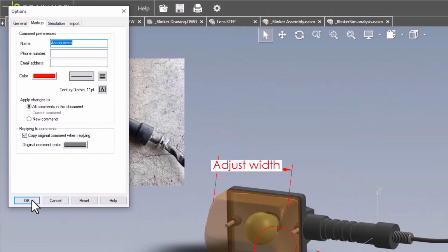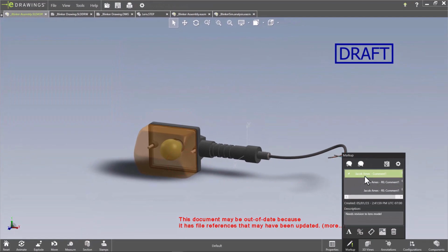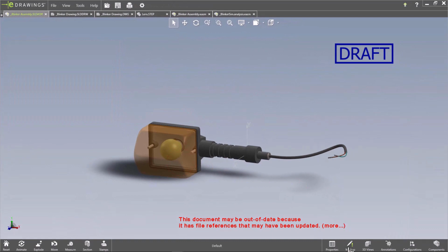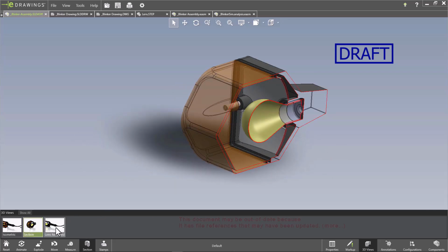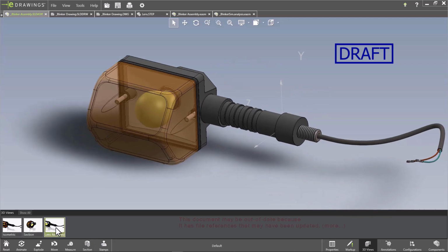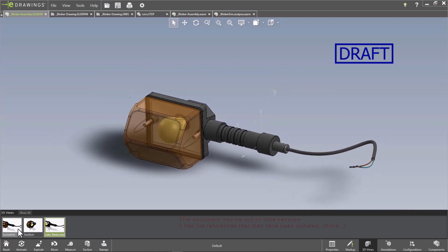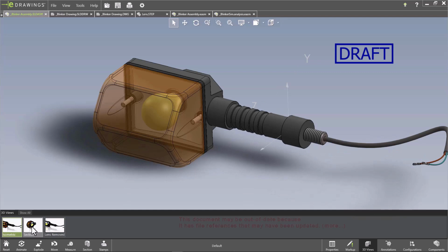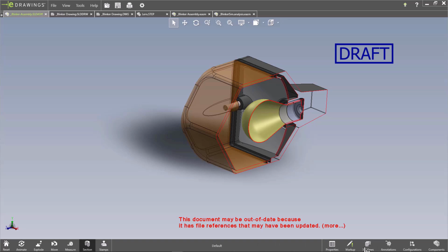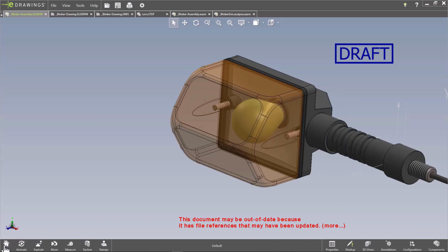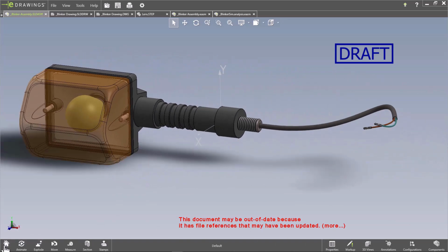Moving on to 3D views, this is a command that many of you will likely not see in the interface. This is because in order to see 3D views, they must have been created in the original SOLIDWORKS document, and this process requires the MBD add-in for SOLIDWORKS. If you do have access to 3D views, the icons can be clicked to quickly toggle between various saved camera positions and model configurations or display states. But do note that configurations and display states are not supported when viewing a native SOLIDWORKS file in eDrawings.